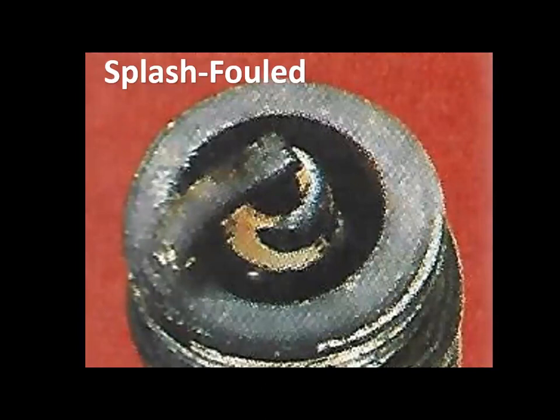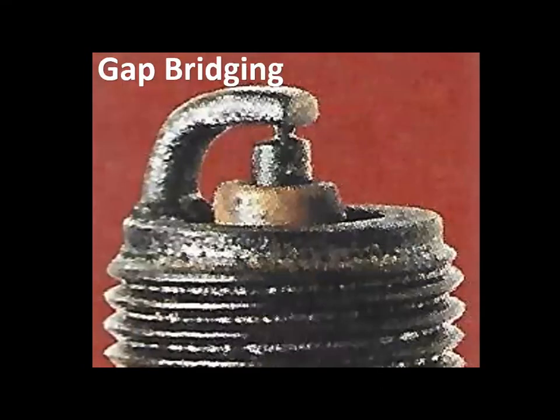Splash-fouled spark plugs have hard carbon deposits splashed on the spark plug insulators. A splash-fouled spark plug is usually caused by combustion chamber deposits that loosen and stick to the spark plug insulator. This condition may occur after a cylinder has been misfiring, allowing some carbon deposits to build up in the combustion chamber. When the cause of the misfiring is corrected, this carbon deposit may loosen and cause a splash-fouled spark plug.